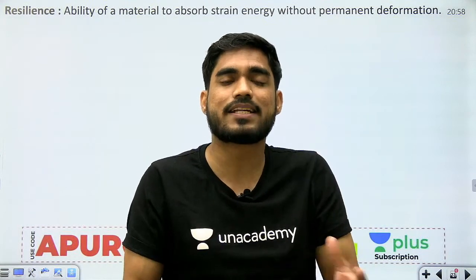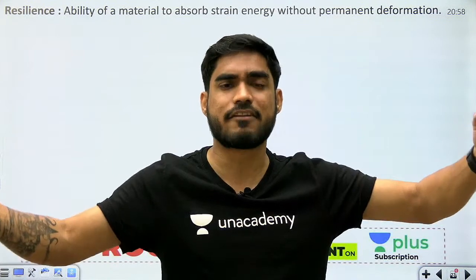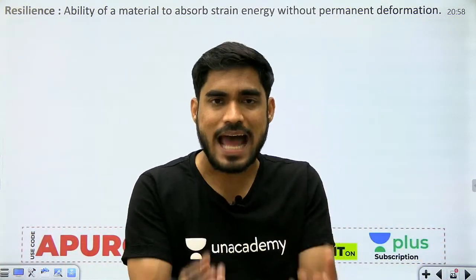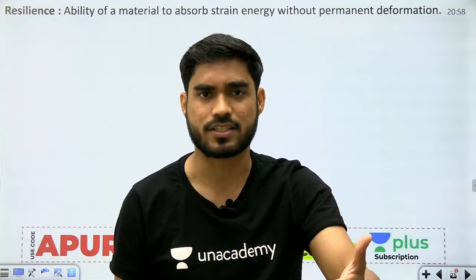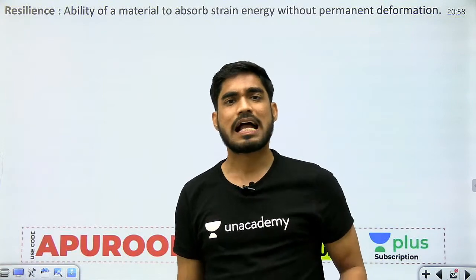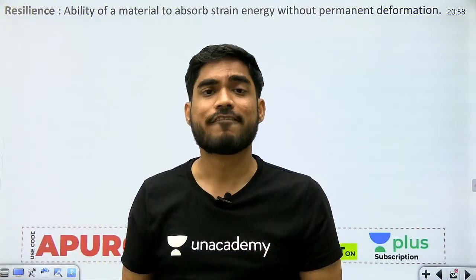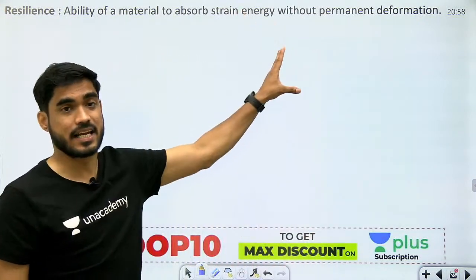This energy is known as strain energy. Just like a spring, when the spring gets deformed, it absorbs some energy, half kx square. That energy is known as strain energy. It is a form of potential energy. Now, how much energy a material can absorb without permanent deformation is known as resilience.